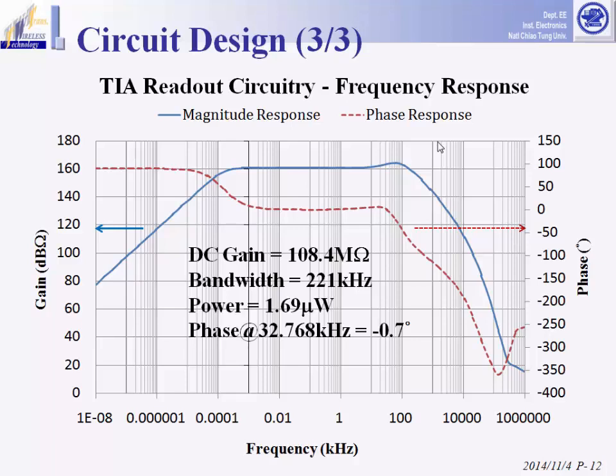Here the inductive peaking was caused by the circuit technique mentioned before, so the bandwidth has been improved and the phase shift at the target frequency was optimized to be as close as possible to 0 degrees.